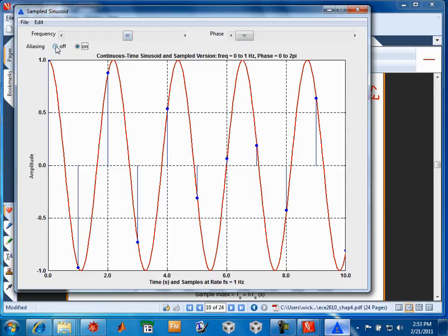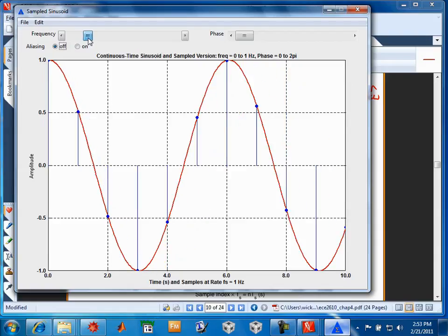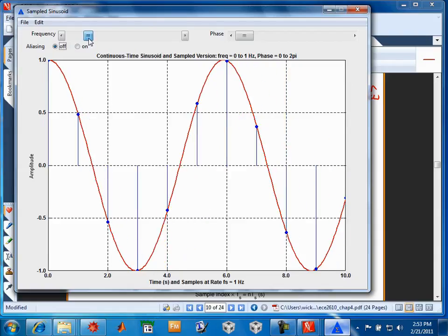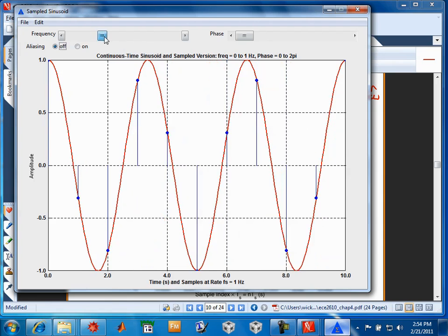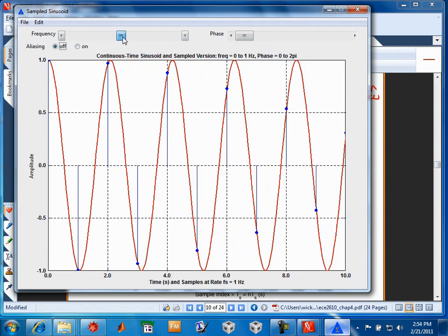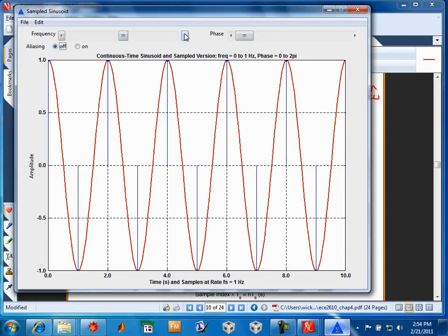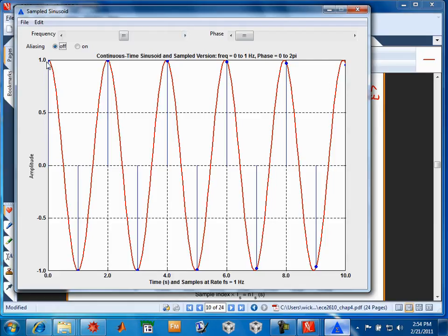One little thing I want to show you that's pretty intriguing, and some people might argue that the sampling theory seems amazing, but the sampling theory says you have to sample at greater than twice the highest frequency. And here's the intrigue factor. If I set this right at the sampling or the folding frequency, so I'm getting 2 samples per cycle, you can say, okay, that's good enough. I have a sample at that peak, and that peak. I can reconstruct from those samples because I have 2 samples exactly.